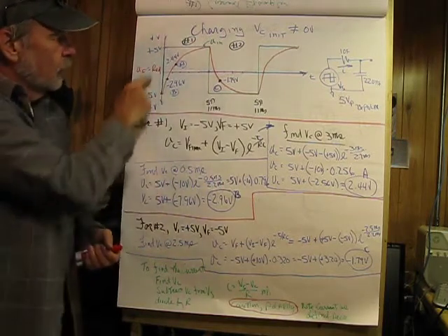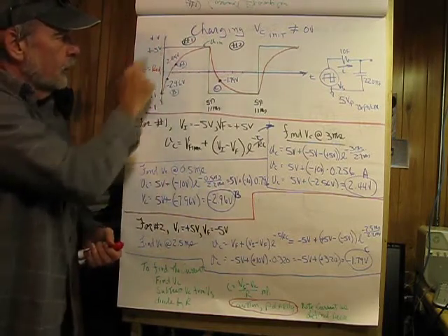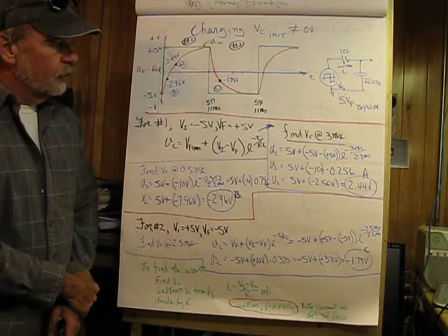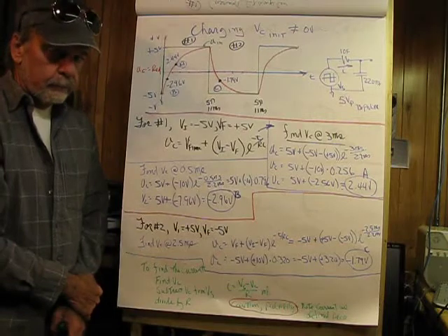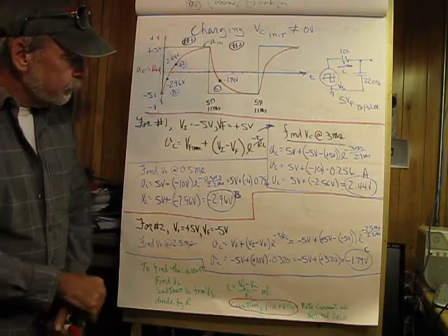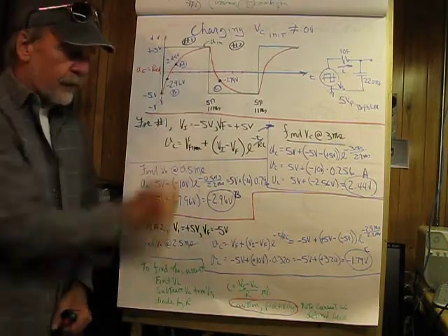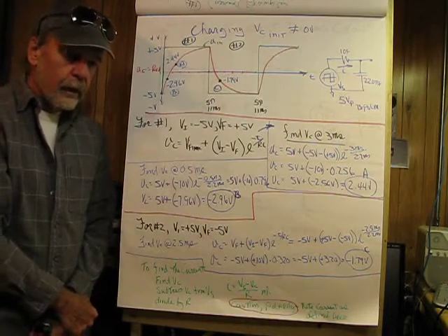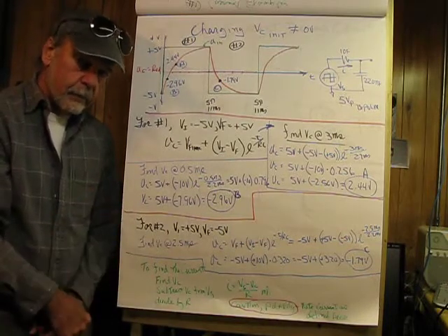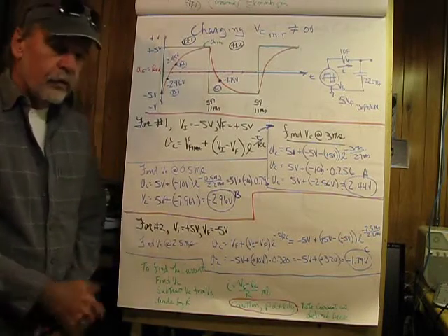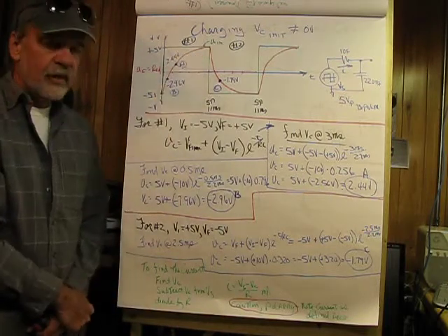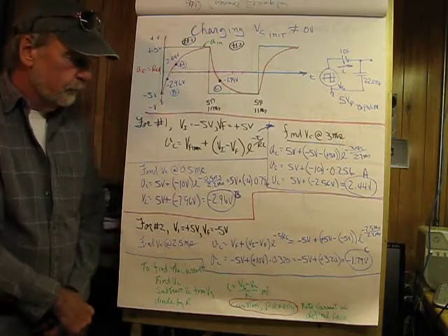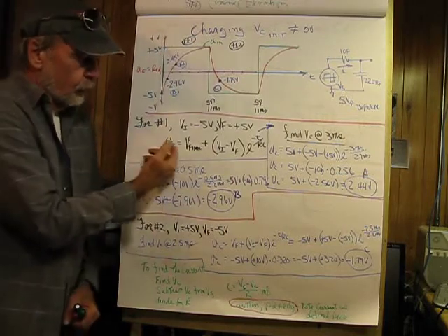And our final voltage, what we're charging to, is going to be 5 volts. Once again, for this to work, our 5 time constants has to be greater than the period divided by 2, so that at 5 time constants we can basically reach the final voltage. So this is where we're going to start here.